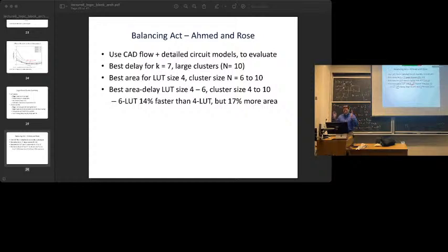You just say, I can make any FPGA size I want, and then I'll come up with the area that this benchmark circuit needs in that FPGA. Does that make sense? And that is essentially the continuous approximation to what you end up building, right? If you had infinite money, that's exactly what an FPGA vendor would do. We built you 1,000 FPGAs, so you can always choose the exact right one. They're never going to do that because the NRE is insane, so you have to round off. But that round off is not useful in architecture studies. It just adds noise. Does that kind of answer your question?